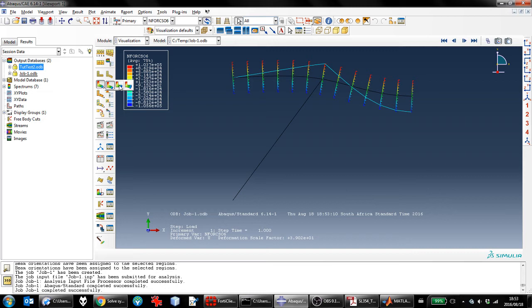Sometimes it's nice to just show it in the undeformed shape. It's easier to sketch. There's two moments you wanted to have really to complete your sketch. In the sketch, I really just wanted to see the shape. Clearly, it's a non-linear moment. Non-linearity, slightly larger here where the larger part of the triangular load sits. And obviously, you want the moment at this node and the moment at the top there.